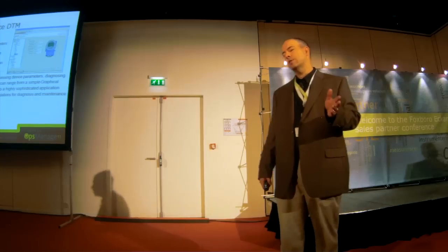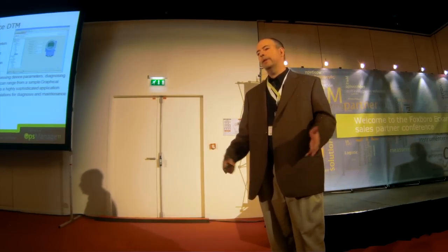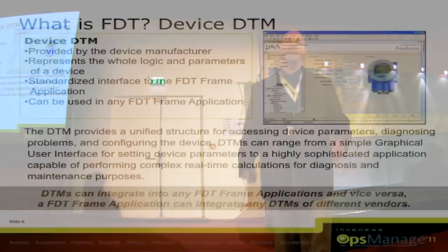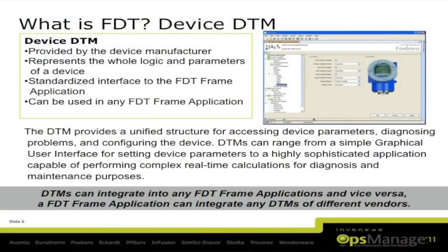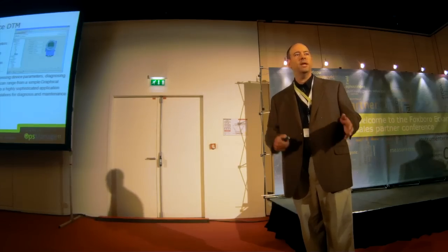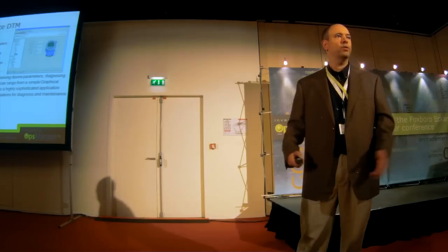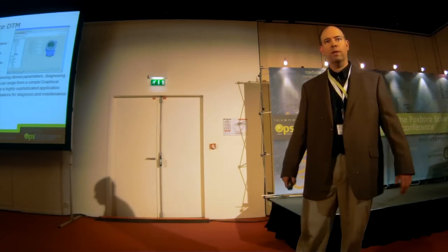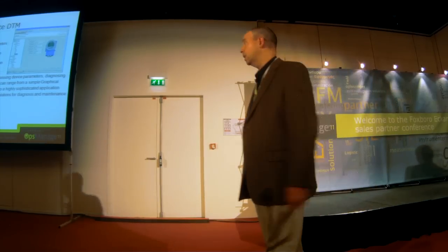As Joe pointed out in his presentation with setting up a custom table, you don't want to do that on an LCD display. You can do it, but it's much easier to do it with a DTM. Meter verification, great feature, something only the DTM can execute right now, and you can get a report. You can't do these kind of things as easily as you can in a DTM as compared to, say, something like a DD or similar. A DD is nice, it'll get you some of the configuration. DTM gives you the user experience. It's a Windows application that we've learned to grow with over the last 20 years of learning, using and leveraging Microsoft technologies.